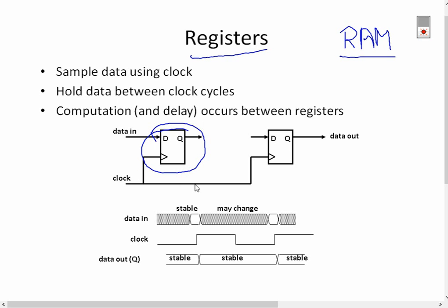To have a register, which is going to store a binary number for me, I would actually have to have 8 of these cells put together sequentially. Its function is that it allows me to hold data between cycles of the clock. Okay? And essentially, that's a register. A register is basically one number for whatever the width of the data is.